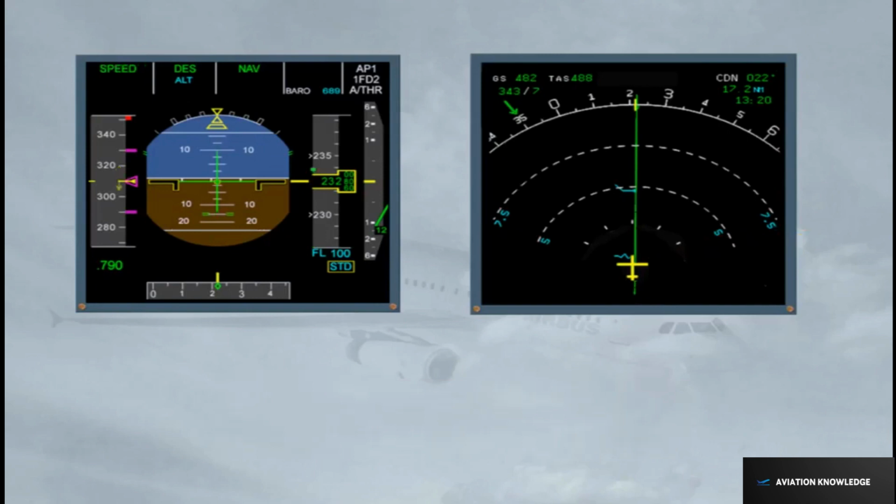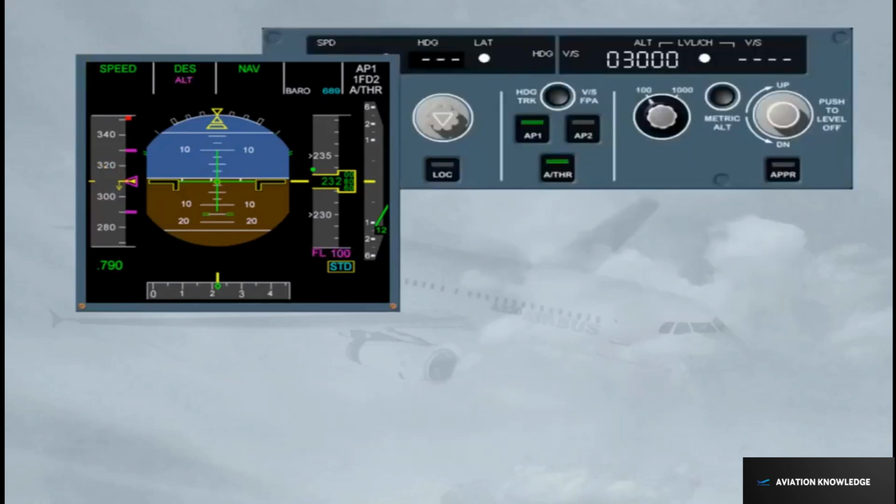If the aircraft is below the flight path, the descent mode will maintain the current speed or lower limit of the speed range until the descent path is recovered. Thrust might be added to recover the descent path. Descent mode respects the altitude and speed constraints when feasible. Altitude is armed in magenta, and target altitude is magenta if the FCU altitude is set lower than the constraint. If the altitude is set higher, then altitude and target altitude are displayed in blue.